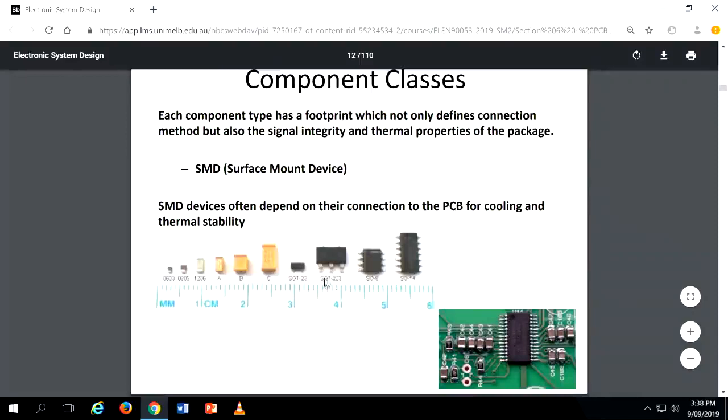SOT means then you will see something like this. Here you got 3 legs, here you got 2. So that is SOT package. That is SOT223. SOT23 means is still smaller and difficult to solder actually, SOT23. So these are the packages: SOT, SOT223, SO8, SO14. Then these are the ICs.